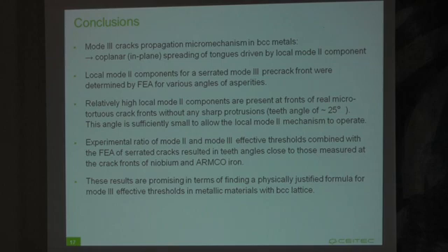So we investigated mode 3 crack propagation in BCC metals which grow by local mode 2 mechanisms, and for the serrated crack front we evaluated local mode 2 stress intensity factor components.